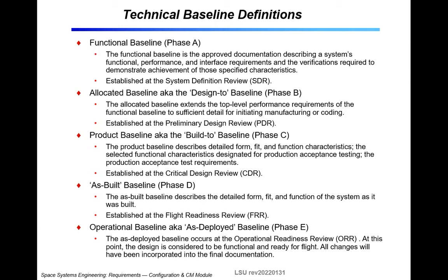Remember, when we first started talking about this, I usually threatened to take all the CDR documents and give them to completely different teams, and then have those teams build the hardware and give it back to the original owner. And so that original owner would have to live with whatever it is that they documented in the CDR. And so here's another expression of that: the CDR is basically establishing the build-to baseline, if you will. And then finally, as you move on into the flight readiness review, you have the as-built baseline, and finally the deployed baseline.